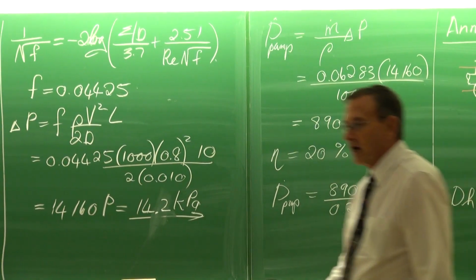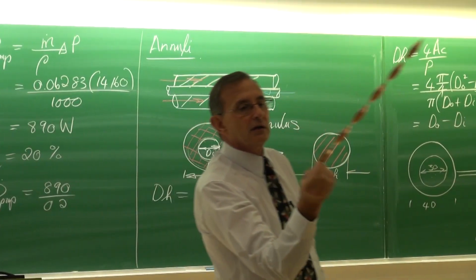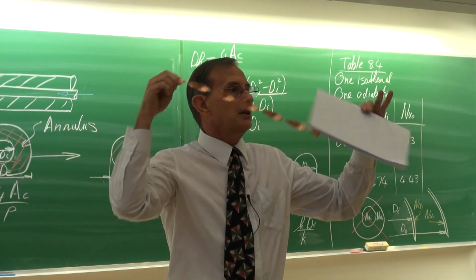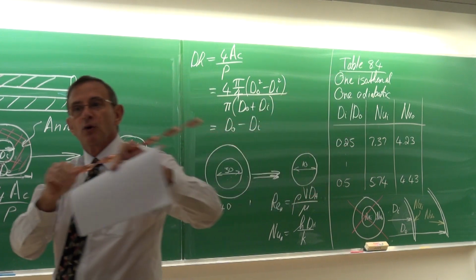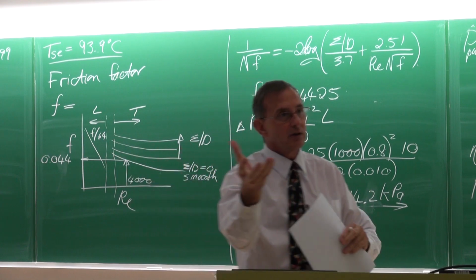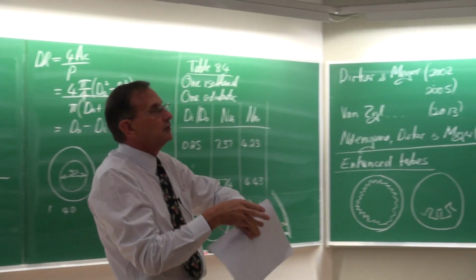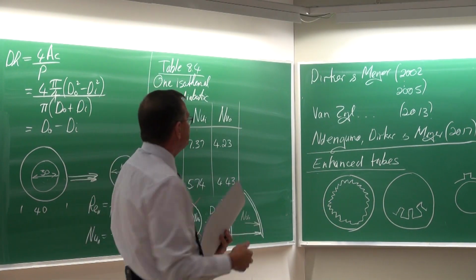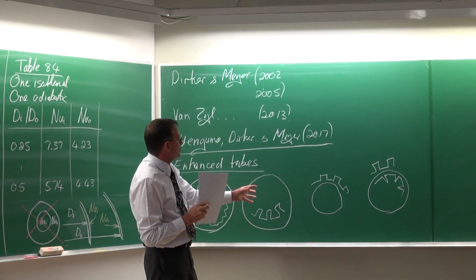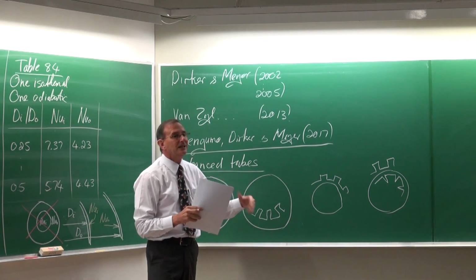One of the simplest ways of doing enhanced heat transfer is to take just a piece of flat plate and just twist it like this. You see? Then you put it inside the tube. What would it do? It would of course rotate the flow. It would spiral it, and that would increase the flow path. Makes it longer and would increase the levels of turbulence. Here the same. All of them would do different types of things to the fluid. The other thing that it does, it actually increases the heat transfer area.